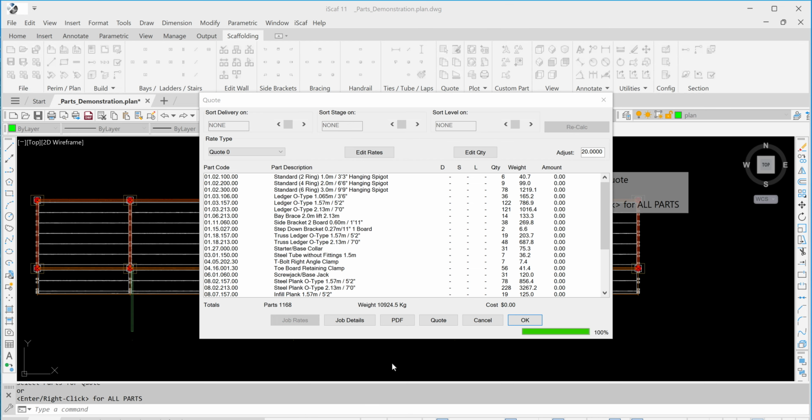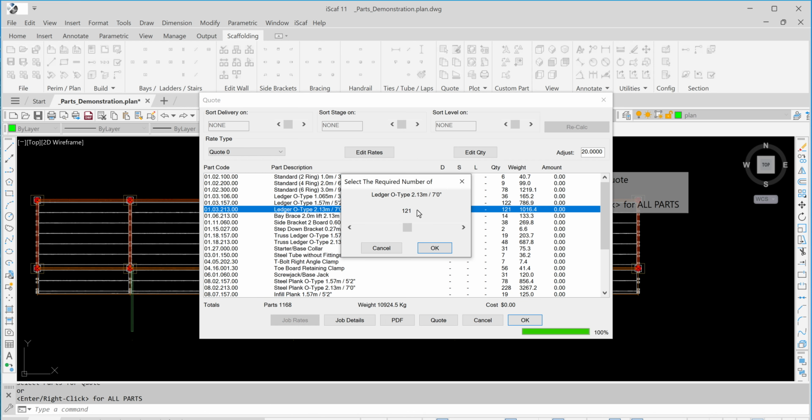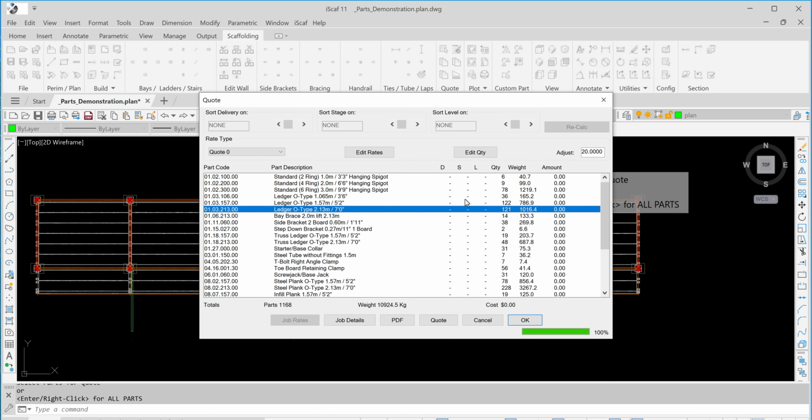When you click Recalc, it actually resets all the quantities back to the original, which means that any edits made by double-clicking are reverted first before the percentage is applied. So that is why when we adjust it by 20%, it changes it from 5 and 8 to 6 and 9, as you can see there for those first two quantities.